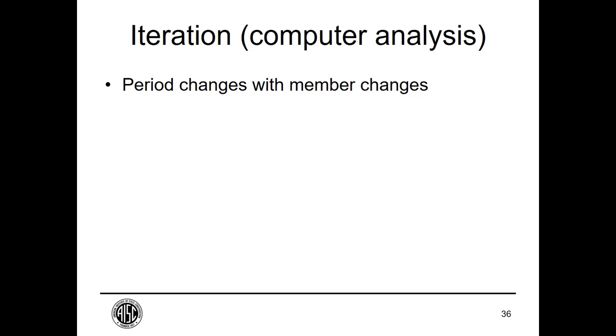Remember that in the computer model, every time you change a member, you are changing the stiffness, and the stiffness will affect the period. The base shear changes with the period.